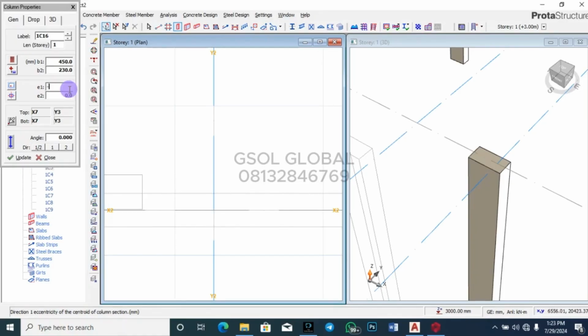All right, so if I insert 112.5 here, I'm actually walking towards the positive direction. So most of the column size would be in the positive direction. If I insert minus 112.5 here, then most of each column size will be where? In the negative direction. You understand? So that's how it works.